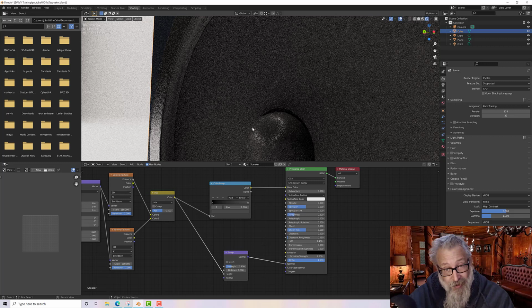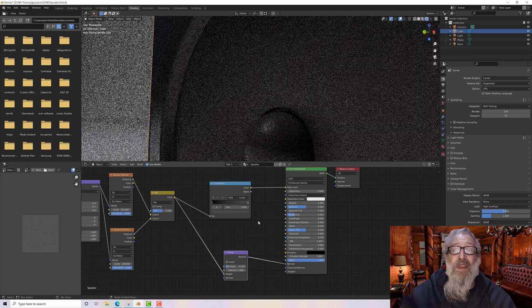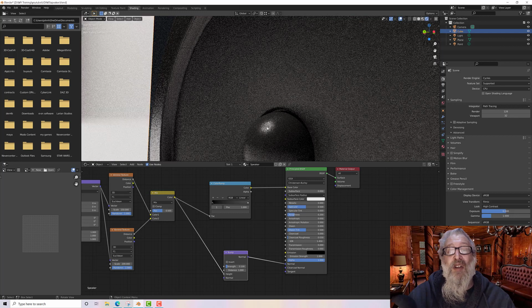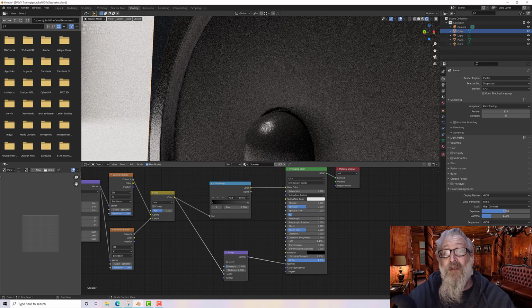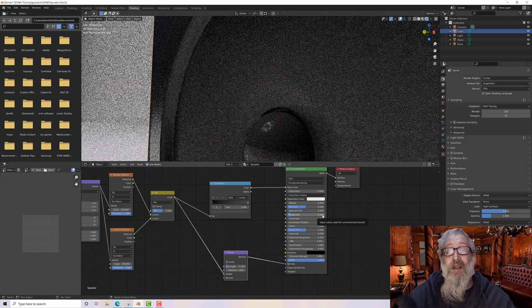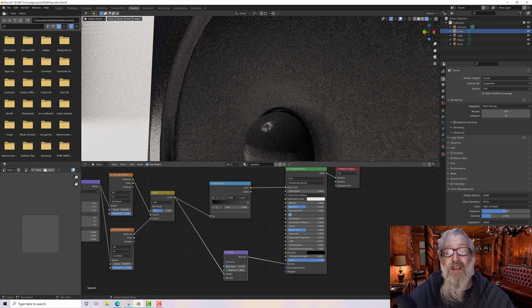In this case, I'm going to accept it, because even though I've updated it and it looks better, I'm getting some shine off it, I'm not getting enough shine off it. So I'm going to take its strength down all the way to 0.1, and I'm getting far more of a concentrated specular there. I could take it down even further, or I could reduce the roughness even further. If I take that down to 0.1, for example, we should get an even stronger thing there. But I quite like the ring effect, so let's pop that back to 0.2.